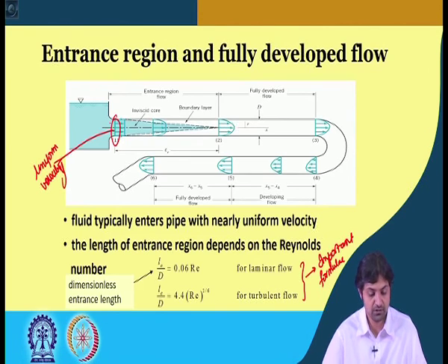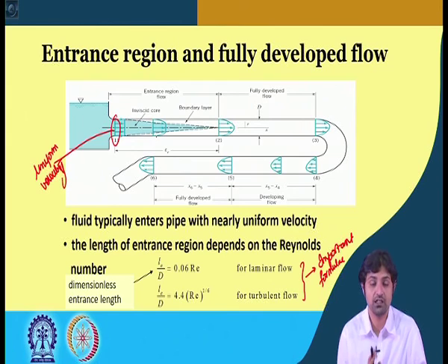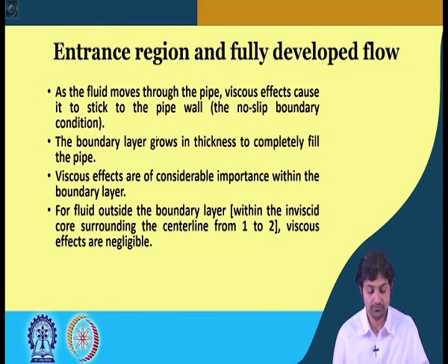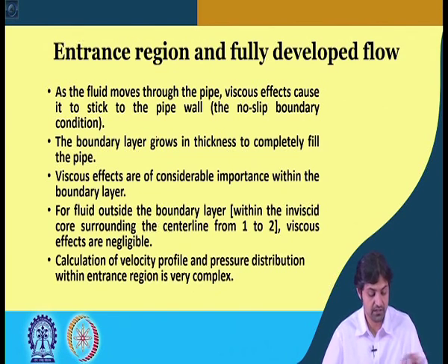This is the inviscid core, that means there is no viscosity in it, but after the end of the entrance region, the boundary layer shall occupy the entire pipe, and the inviscid core will cease to exist.